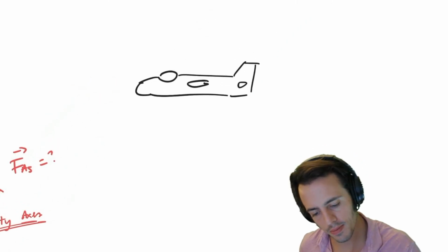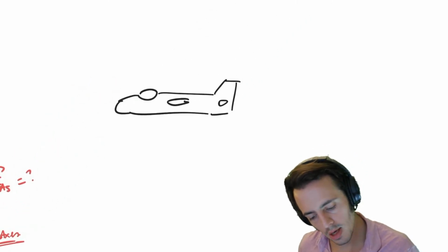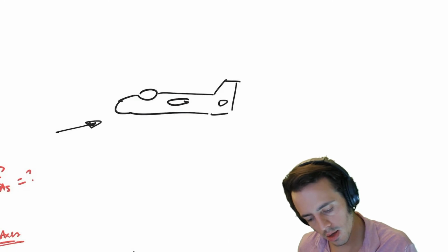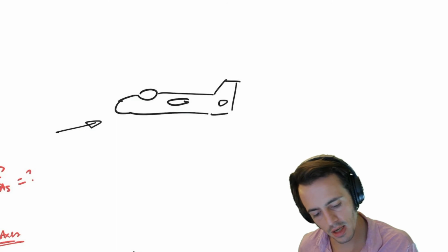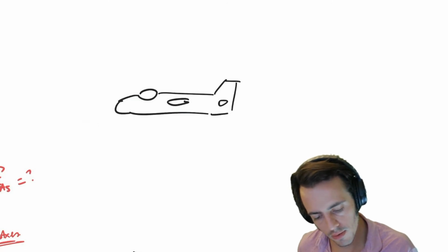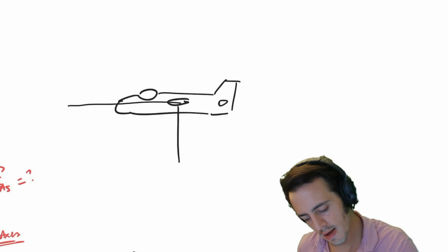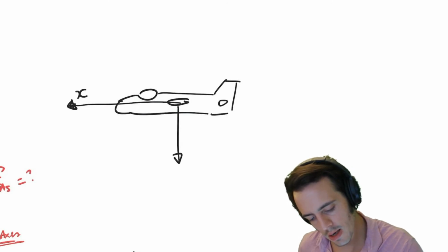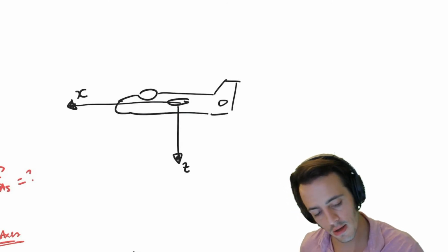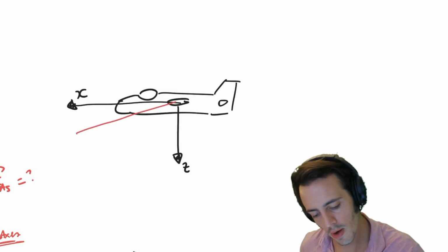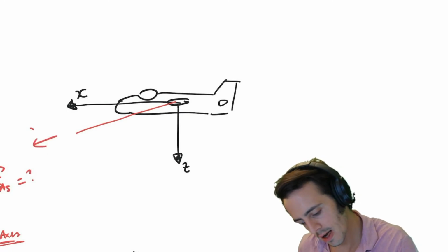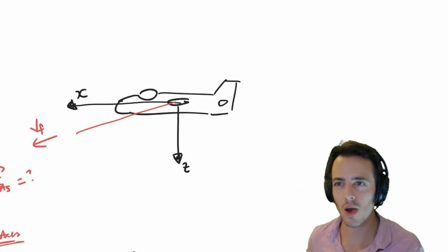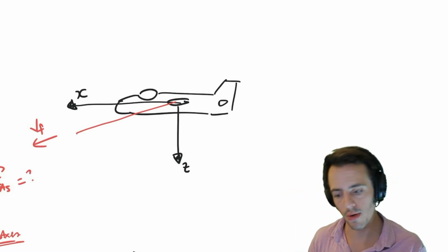If we've got our oncoming flight speed vector, let's draw stability axes in red to be consistent. I will draw on body axes. We're not actually going to use them, but let's just draw them on anyway, because it helps us remember the definition of stability. That's actually our flight speed vector, or that would be VF cosine gamma really, but for our purpose we can just call it VF at the moment.